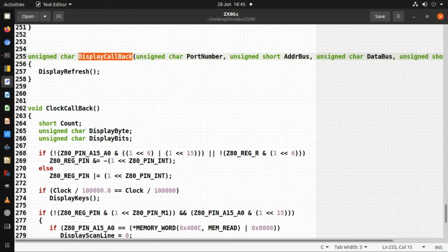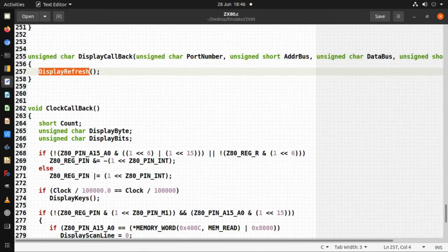During that time it synchronizes the frame, and it does the execution. What the ZX80 and ZX81 do is execute the actual program that you're trying to run during that period, whereas when it's updating the display itself, that's all it does. It just updates the display, it spends all its time doing that. So that's all it does in here, is refresh the display when it comes to that blanking area.